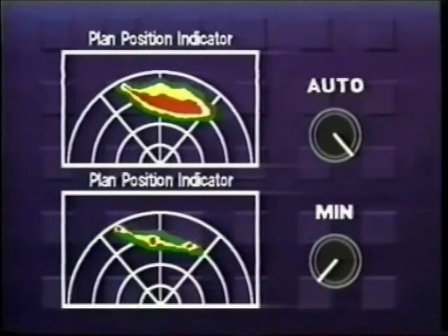The only time manual gain should be used in the weather mode is if you want to use it to evaluate the relative rainfall rate of 2 or more strong storms. When you are finished, return it to auto. If you forget and leave the system uncalibrated, you could get surprised by a dangerous undetected storm.